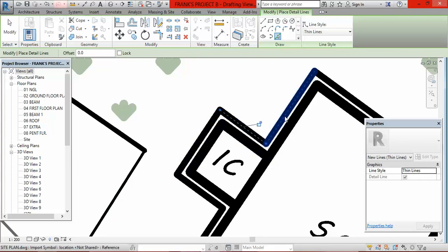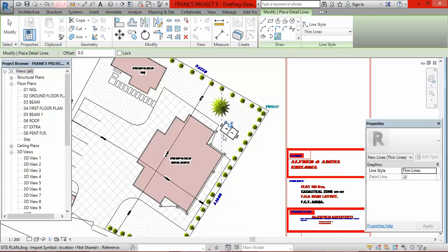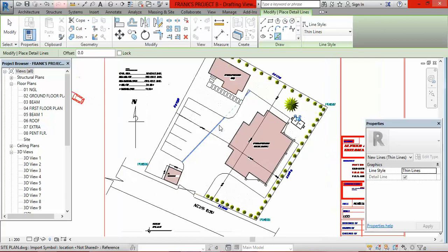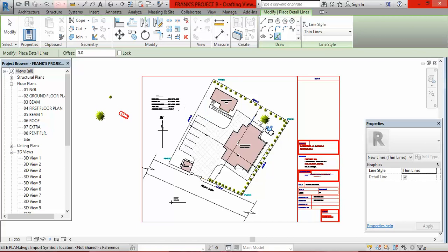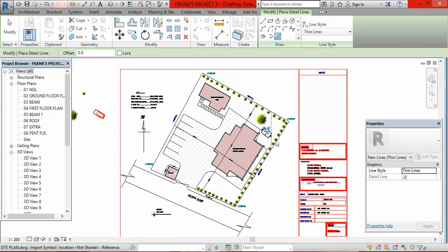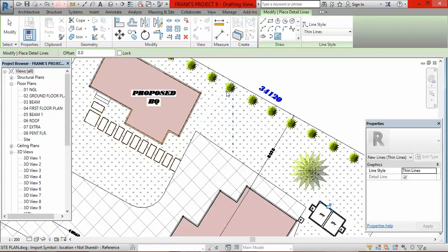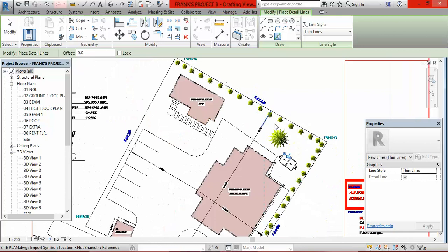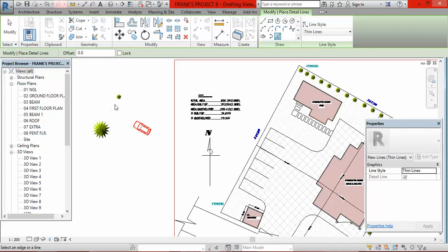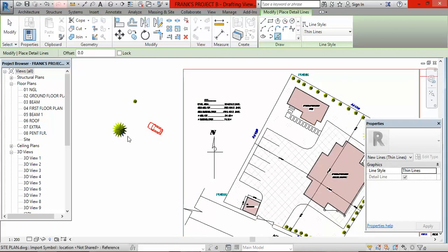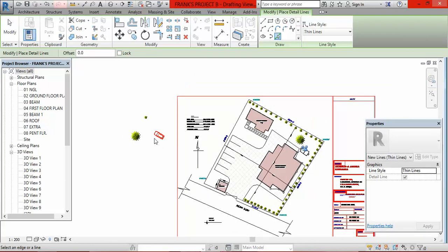So I am sorry, I wouldn't need to do all of this for now, because of time. I want to teach you some other things that you may need to do in your site plan, like creating this text. I've already shown you briefly how to create a text when I went to text there. But what happens when you want to bring in something like trees like this? Because when you want to delete this AutoCAD file, all of these trees are going to go away, including the car. So this car that I brought here, I did it for a reason. You are going to go to AutoCAD wherever you have these objects and load them individually. When you load them individually, you can now export